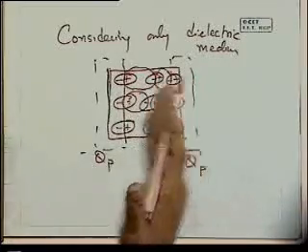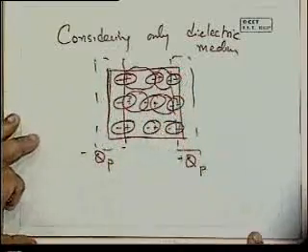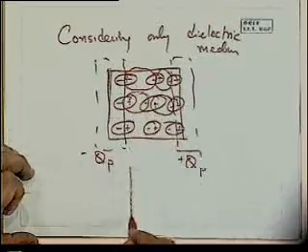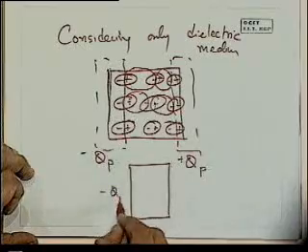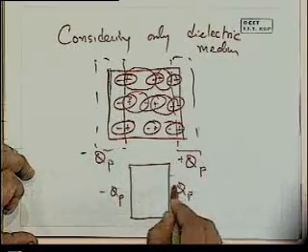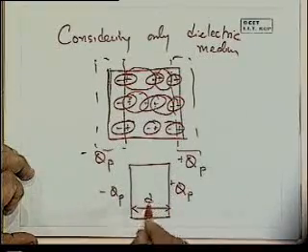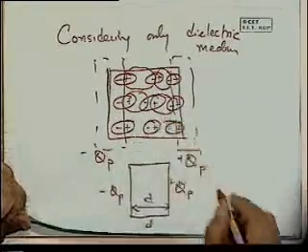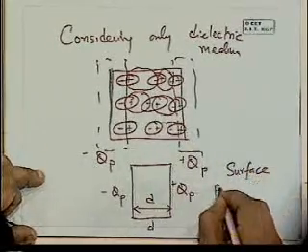On the surface, we've built up a negative charge here and a set of positive charges here. If you forget about everything else, you can simply draw it as the dielectric now having minus Q_P on this plate, plus Q_P on this plate, and the separation is simply d. These charges are bound inside the material and are called surface polarization charges.